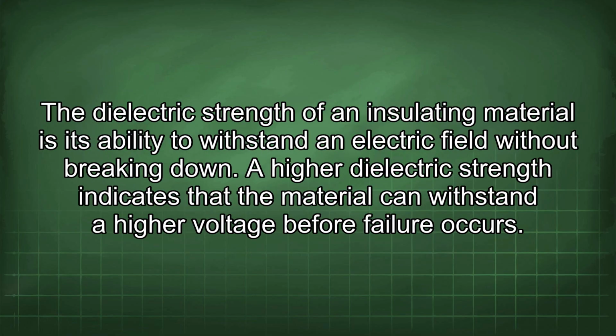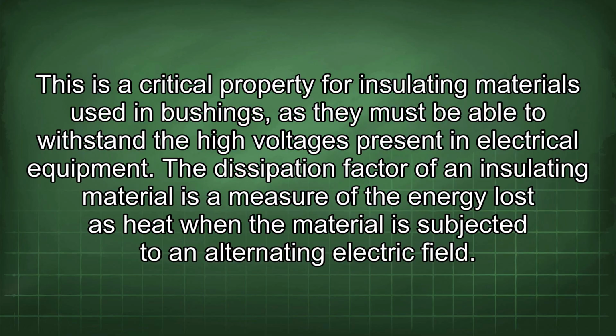The dielectric strength of an insulating material is its ability to withstand an electric field without breaking down. A higher dielectric strength indicates that the material can withstand a higher voltage before failure occurs. This is a critical property for insulating materials used in bushings, as they must be able to withstand the high voltages present in electrical equipment.